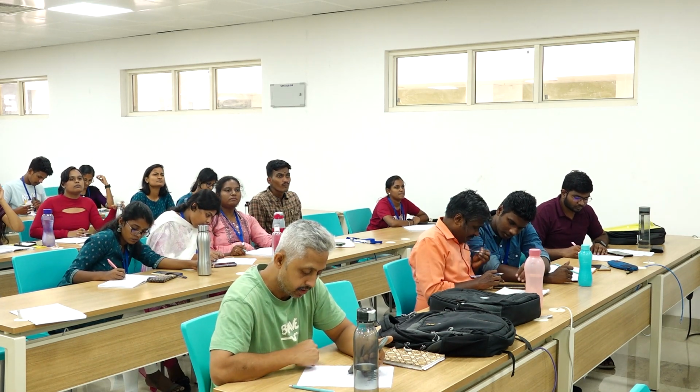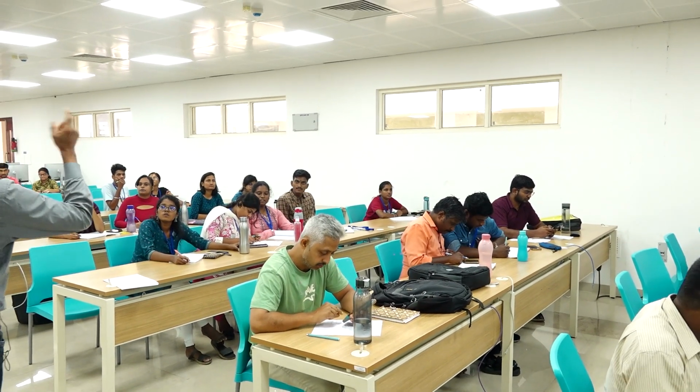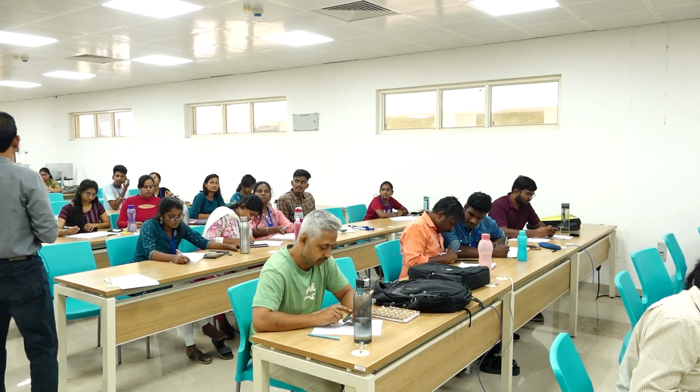What is this? Yeah, okay. The second one, most of them got right. So go to the next, then you will get more practice. Do it. I just put the fill factor. So this also you have to use the PCE first, because you know the PCE and JSC, VOC, and power input. Just take it as 1 and calculate the fill factor. You use the PCE formula. So Pin should be 1 actually. Don't convert any value, just take the value as it is.